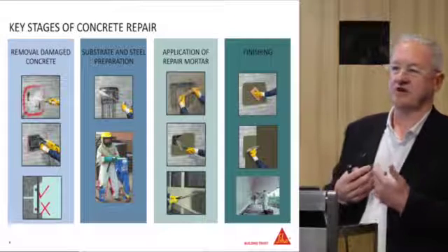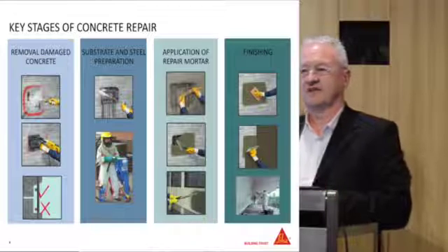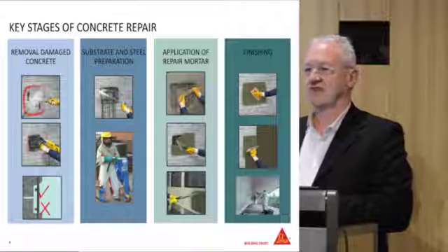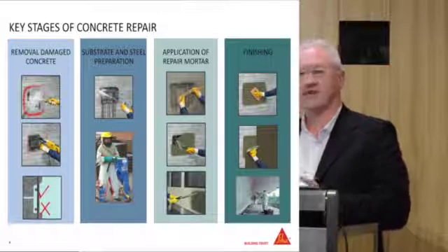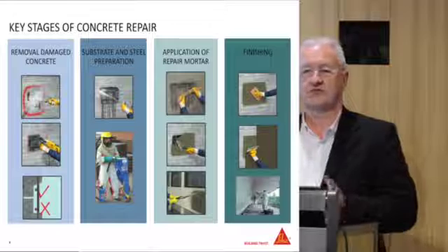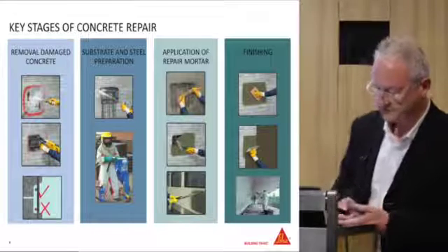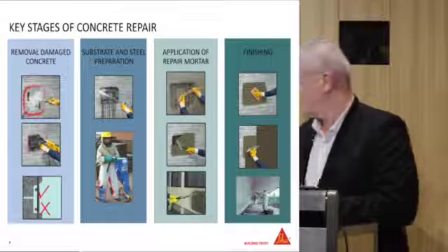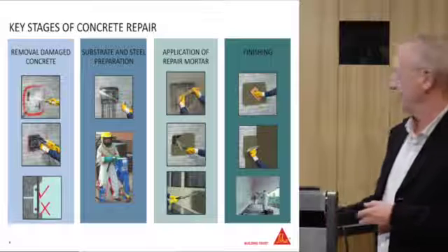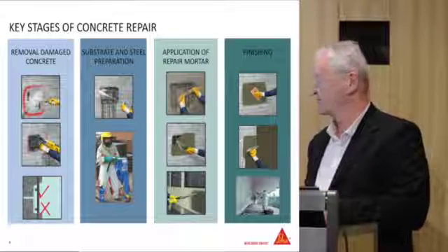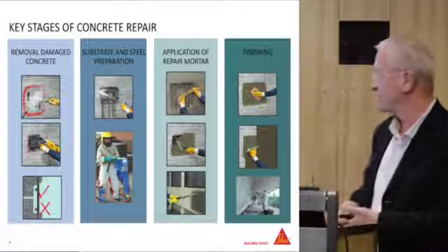From our point of view at Sika, we only supply R3s and R4s. We don't really think you'd need 3 types of non-structural repair mortars on there. And R4, you've got no choice with one particular product, which is, say, a structural repair mortar. And you can either apply them using different techniques, hand-placed or machine applied, and I'll come into the application processes in a few minutes.